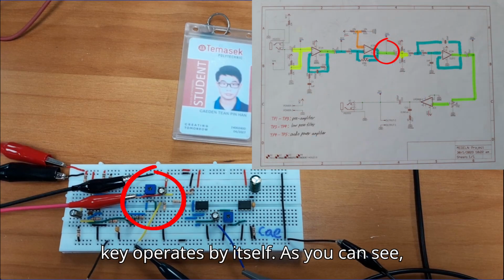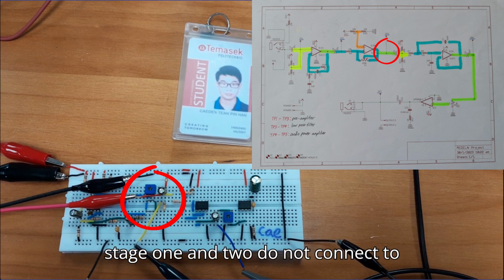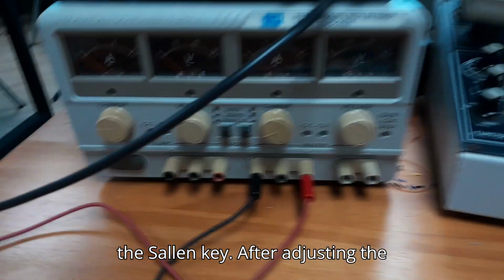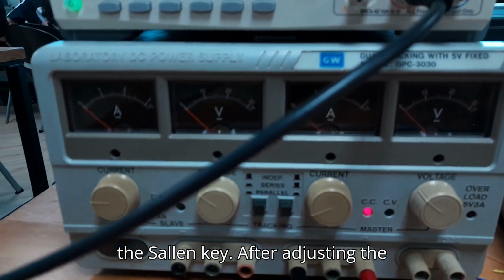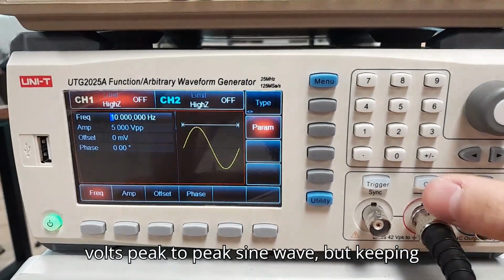Moving on to the oscilloscope, I will first show the waveform when the Sallen-Key operates by itself. As you can see, I disconnected the green wire such that stage 1 and 2 do not connect to the Sallen-Key. After adjusting the function generator to be at 10 Hz, 5 volts peak-to-peak sine wave, but keeping the DC power supply untouched,